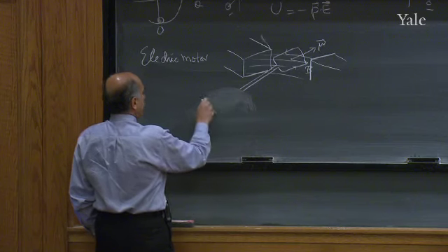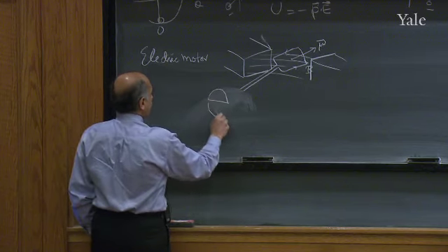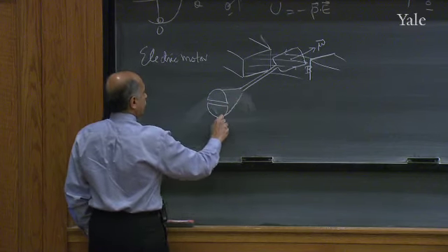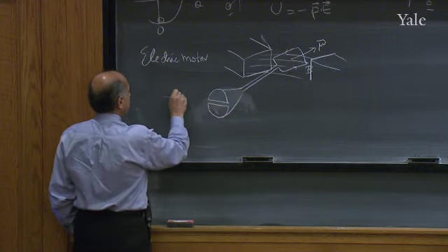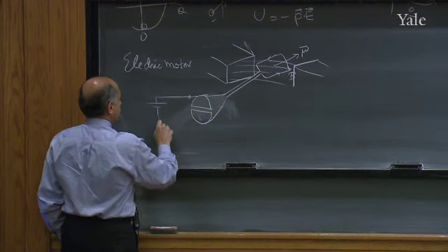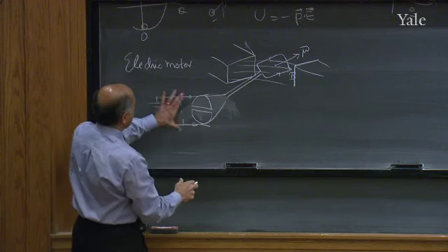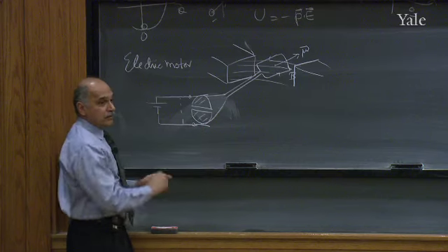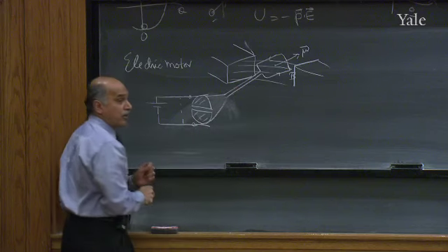These two wires feed into two semicircular pieces of metal. Okay, imagine that comes there, that comes there. I've just blown it up for your view. Then the battery is connected like this, not with a hard wire, but with a spring-loaded brush. Okay, there's a brush here. That's a spring holding it. So these brushes make contact with these two metallic hemispheres, if you like, semi-cylinders, which are then connected to this wire.